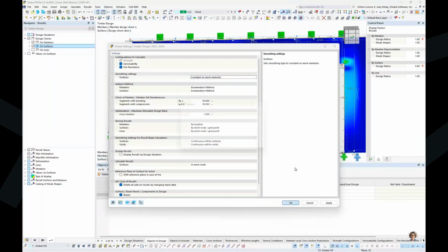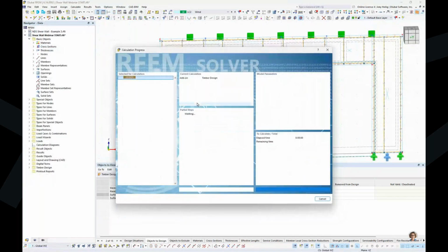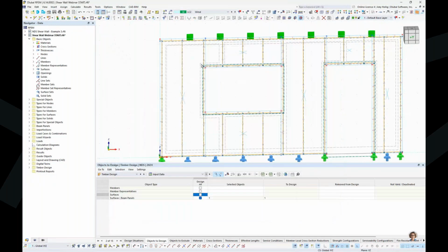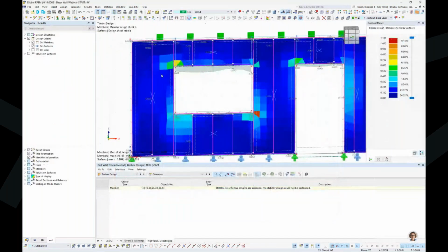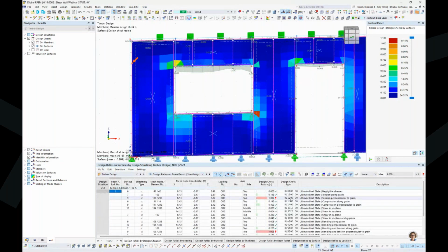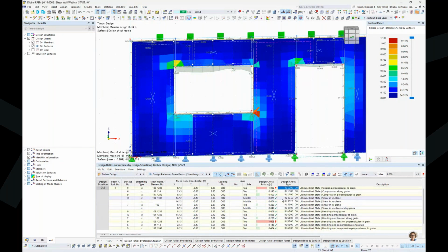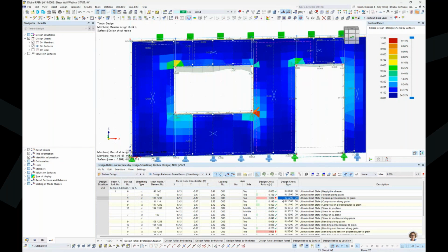So to me, this is just a very quick, easy fix to this singularity problem, in the sense that we're no longer going to try and tie together all of the results here with nice colored contours, but we're giving you exactly one result here per FE mesh element. So this could certainly be, again, a very quick kind of Band-Aid fix to those singularity issues. Now we see there are a couple locations that are still slightly over 1.0, but for the most part, our design check looks quite a bit better. But probably best approach is the FE mesh refinements, again with the surface result adjustments.